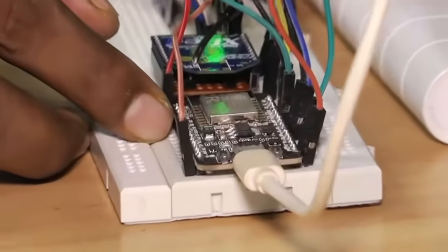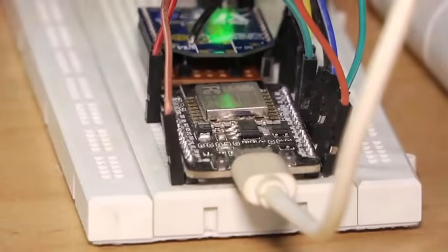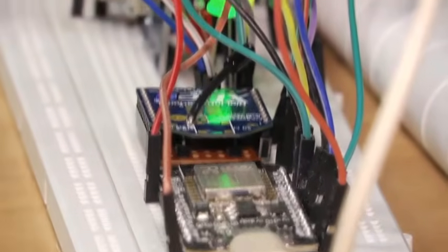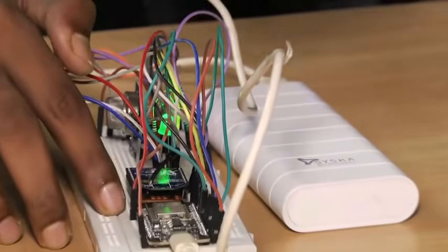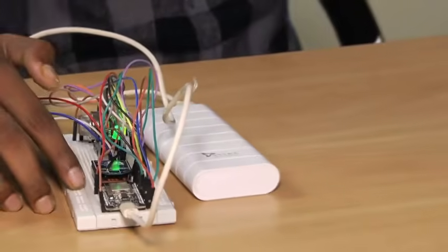In the second node we use the Arduino, and between the two nodes we communicate through Zigbee. This node sends the data through the Zigbee device, and the other node sends it through Wi-Fi to an MQTT broker, which I installed in my local server. Here is the nearest fire station, which can subscribe to the topics used in my MQTT.